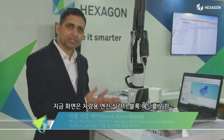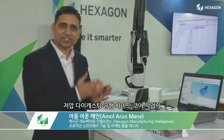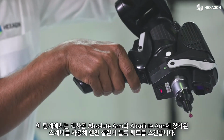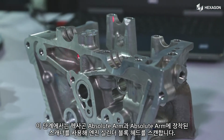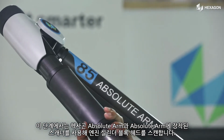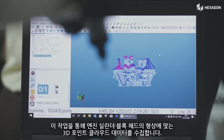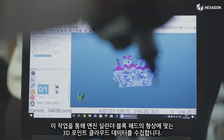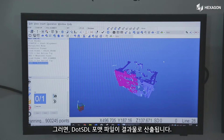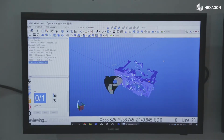Here we are showcasing a smart factory workflow for the side core of a low pressure die casting die for the head of an engine cylinder block for a car. At this stage, we are scanning the head of the engine cylinder block using Hexagon Absolute Arm, which is a scanner. We collect the 3D point cloud data corresponding to the geometry of the head of the engine cylinder block, and the .stl file format is the output.